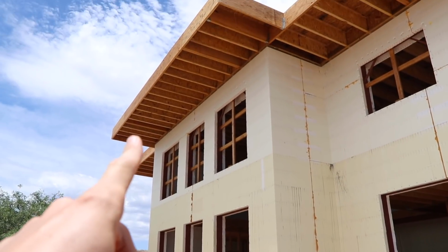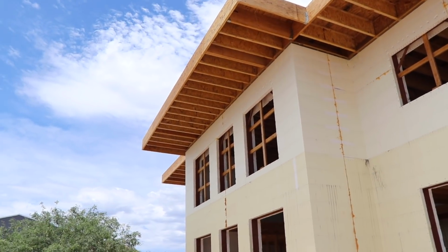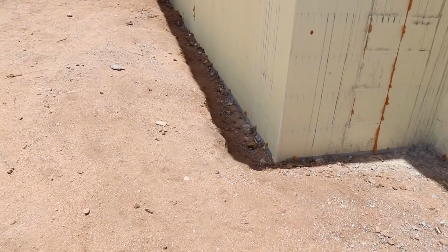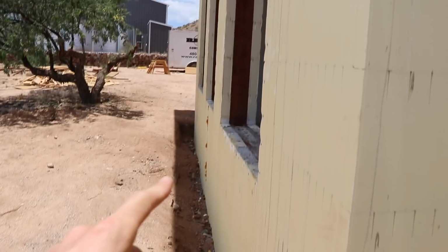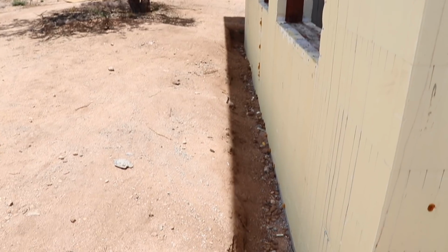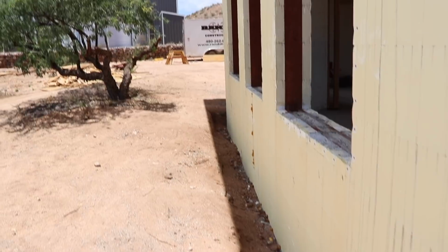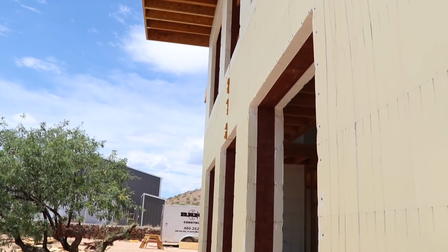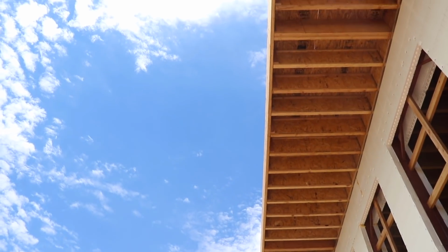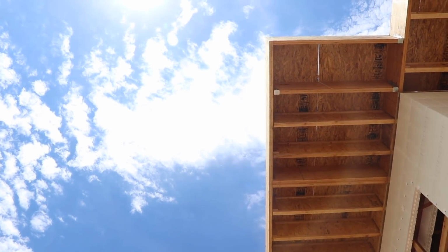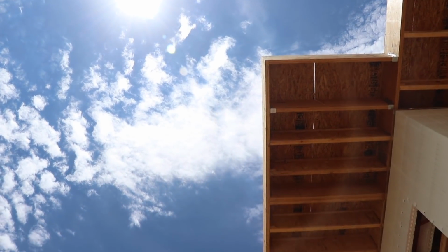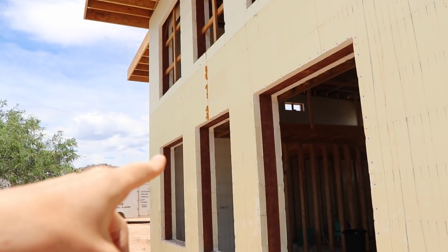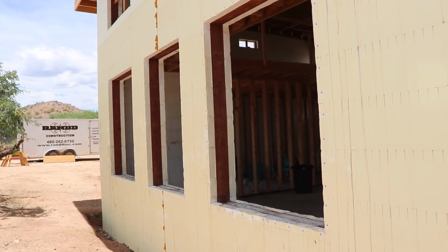And right now we've got a massive 5-foot overhang, and you can basically come down here and see that we're not going to get any solar gain coming in through these south-facing windows. During the hottest part of the year, you can see that our overhang is basically casting a shadow over the south side of the building. We're almost at about noontime, and that's when the sun is obviously going to be highest in the sky there. So we're basically going to keep all these windows shaded throughout the summertime, and we're not going to get any gain coming through those windows.